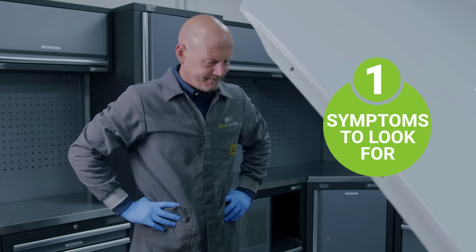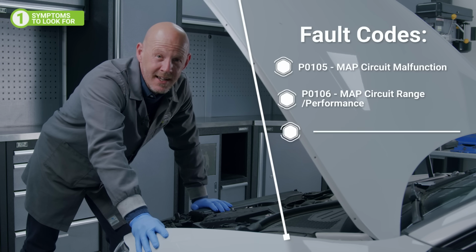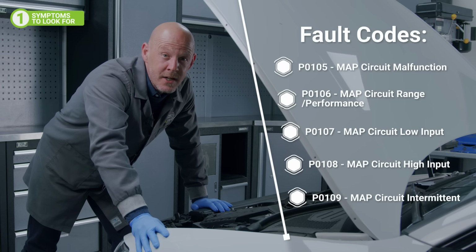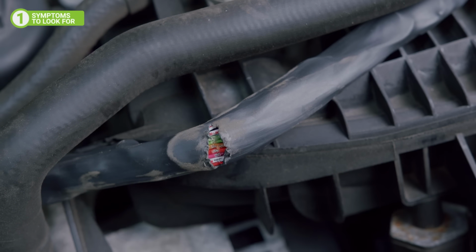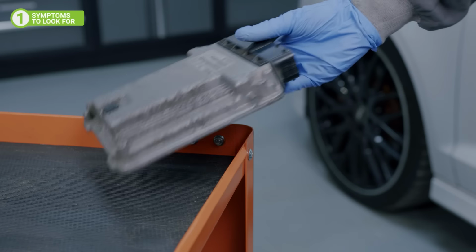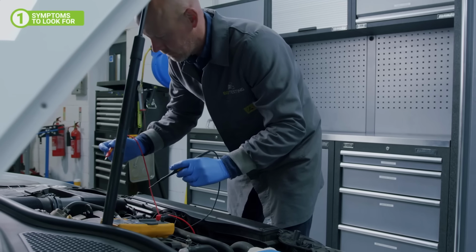When this sensor fails, you can expect everything from poor engine performance to a range of MAP-related fault codes. Like almost everything on our vehicles nowadays, these can be caused by electrical issues like damaged wiring, corroded connectors, internal failure in the sensor, or a faulty ECU. Thankfully though, we've got a few checks you can run through to get to the bottom of this.